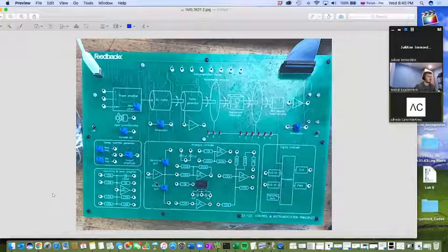So yeah, positive or negative in the power amplifier relates to keeping a negative feedback system, right? I think that's one of the first chapters that you did in the lab, checking the polarity of the loop. Positive feedback systems are useless, right? They do not give anything to your responses. So you want to always keep a negative feedback system, and this relates also to the stability of the main